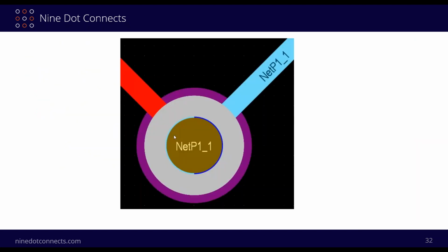In fact, I purposely did this so you can see this a little bit better. It's not easy to see on here, and I wish Altium would make this a little bit thicker, but nevertheless, it's there. So what you're seeing here is the same color, which always represents a through hole. So you don't see a split chip in terms of one color on one side and another chip on another side. That's reserved for blind and buried vias. So it is showing the through hole.